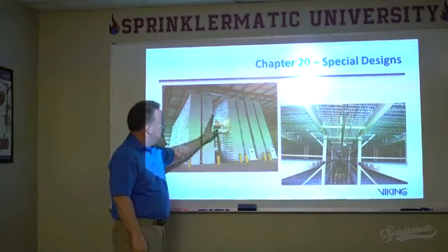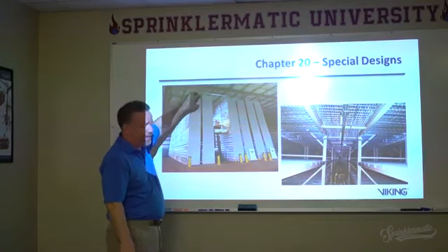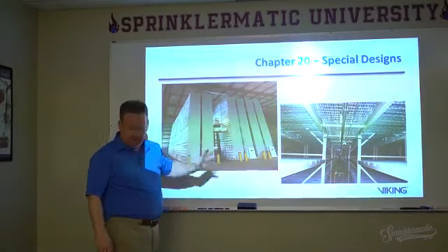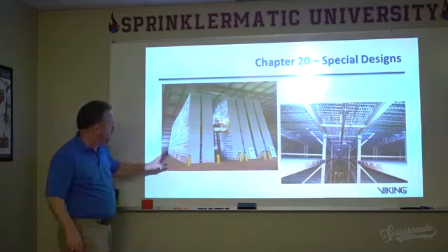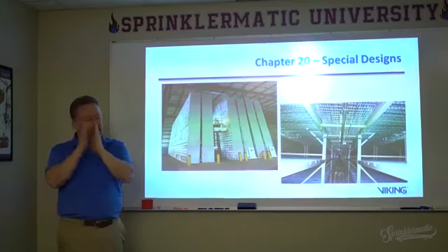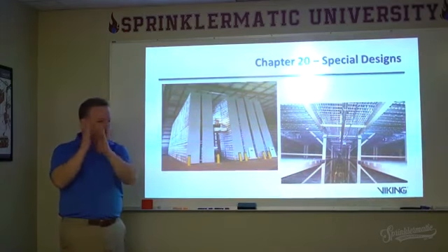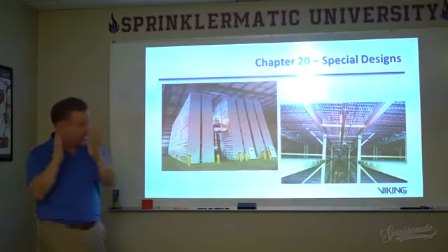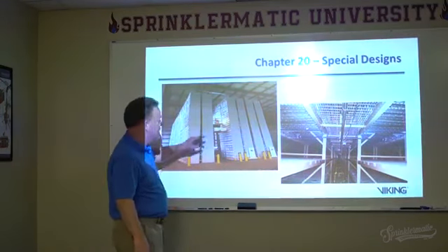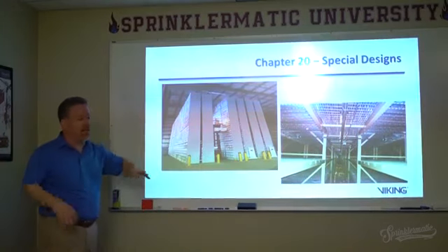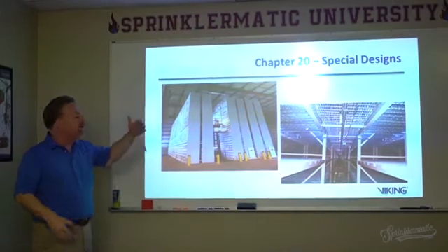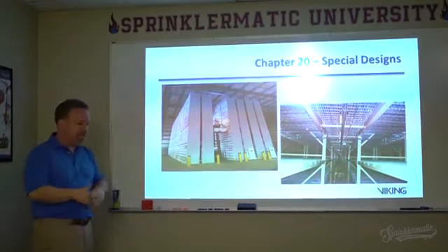In this case, we have a very tall, like a 50-foot high, compact record storage facility. This is a federal government facility, but it is basically like those compact shelf storage units that move in the doctor's office or the lawyer's office. These are the same thing. It's archive storage. So there's a special design. In NFPA 13, nowhere else in the document can you find this particular arrangement. You have to go to Chapter 20 for the specific design.